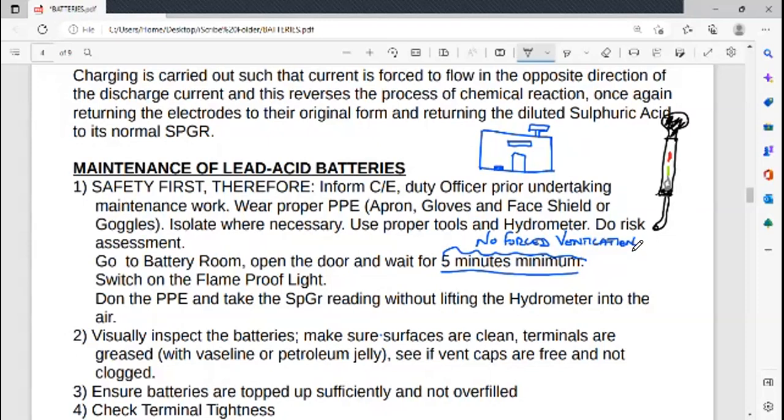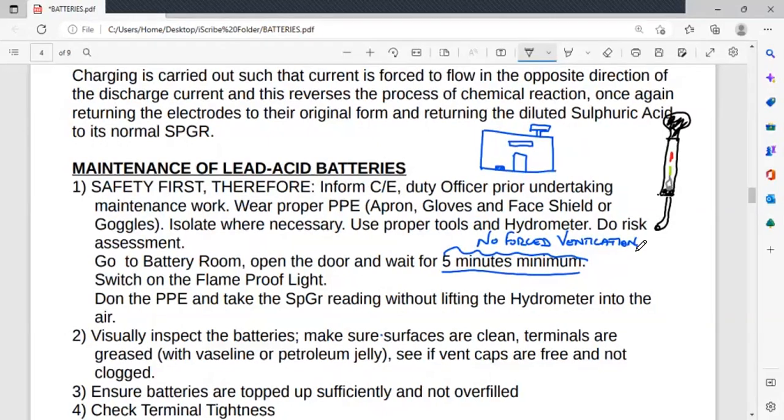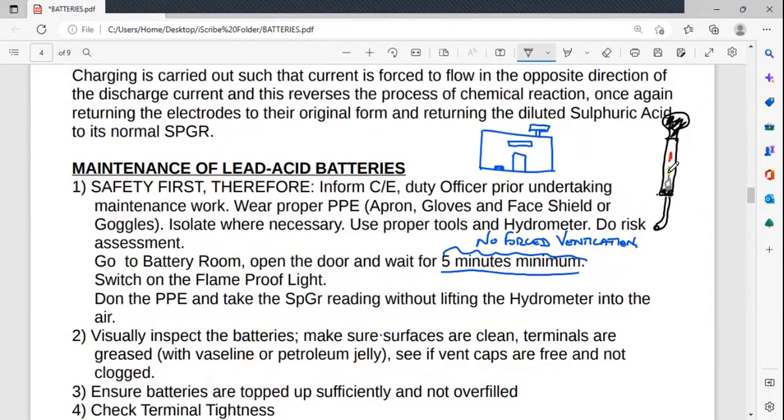We're not talking about maintenance-free lead acid batteries. Those are sealed. So you would open those vent caps, insert this into the opening, and press the bulb, extracting not too much. It should be such that this bob just rises. The bob has a lead over here, and because of the specific gravity, it is going to rise. Don't pull it up so that it gets stuck.